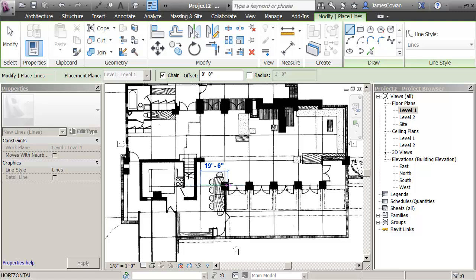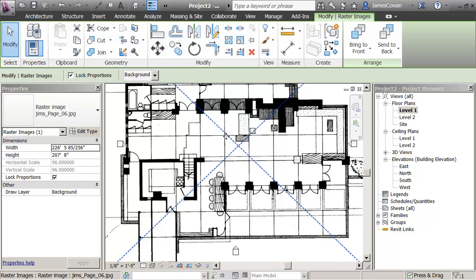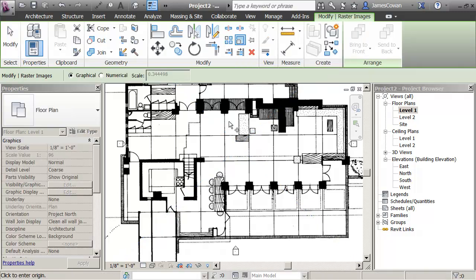So what I want to do, I want to select the image, I want to pick on the scale command, and I want to give it as big a distance as I can from the model. So when I click on here to say about there, it says 105, but if I count my squares 1, 2, 3, 4, 5, 6, I actually know that's 36 feet. So after I've given it the second point, I then type in 36. That's the size that I want those 2 points in the image to measure as.